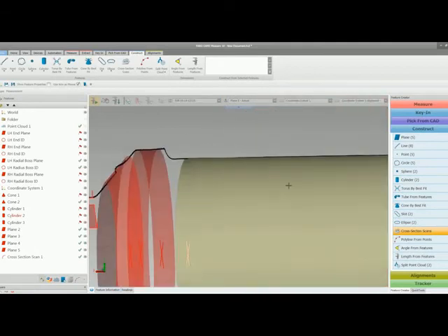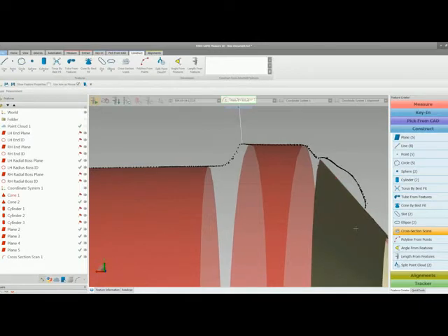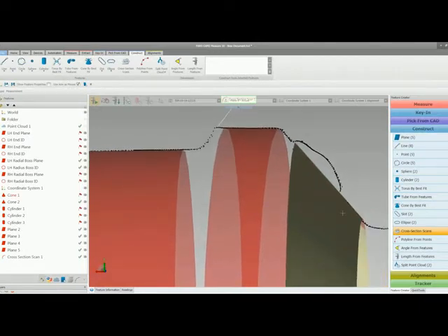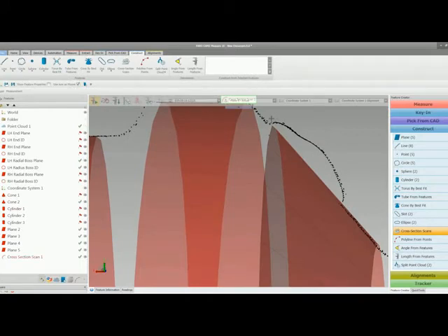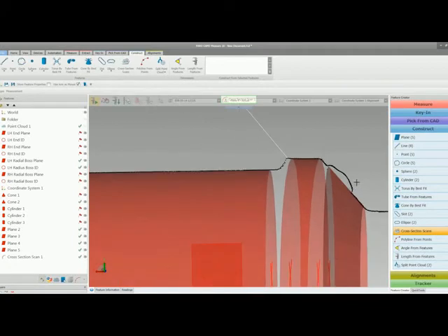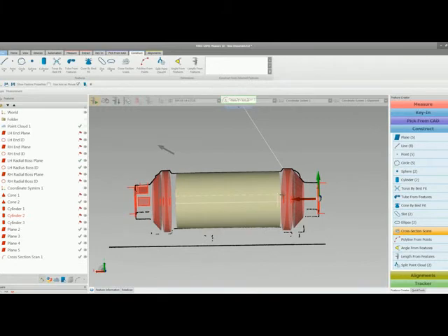It's a line of points that follows the surface of the CAD model. And you can see here that here's one of those pieces of putty that I glued on here, which if I polygonized this and took it into CAD, it would take a lot of cleaning up to get rid of that feature. But on here, when I get into CAD with the polylines, I can literally cut this section of the curve out and repair it, and within 30 seconds I've got a good curve on there that I can then rotate around the center axis of the coordinate system, or the center of the cylinder, and create the unblemished body of this particular part. So it can save you an awful lot of time using cross sections rather than going to polygons.